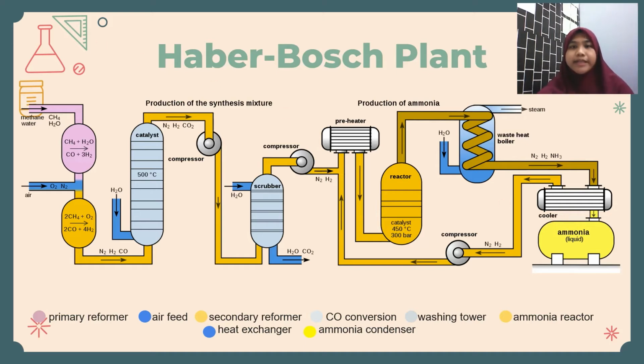Depending on its origin, the synthesis gas must first be freed from impurities such as hydrogen sulfide or organic sulfur compounds, which act as catalyst poisons. High concentrations of hydrogen sulfide, which occur in synthesis gas from carbonization coke, are removed in a wet cleaning stage such as a solvent process, while low concentrations are removed by adsorption on activated carbon. Organosulfur compounds are separated by adsorption together with carbon dioxide after carbon monoxide conversion.